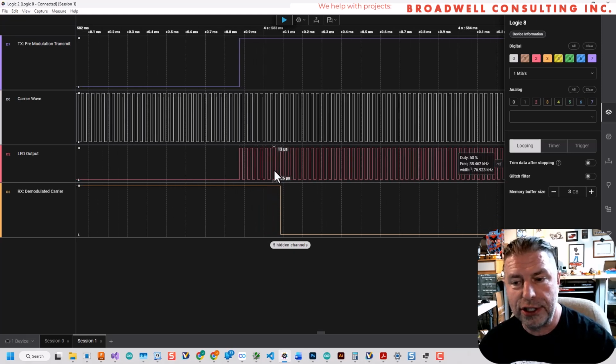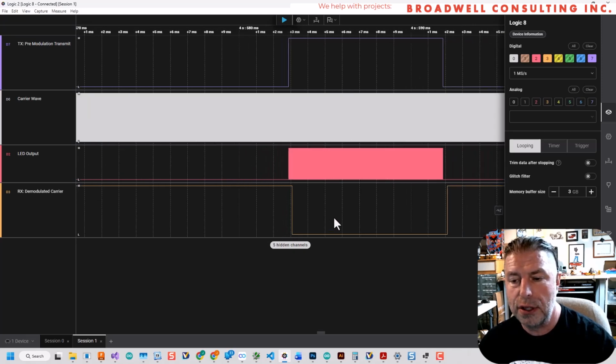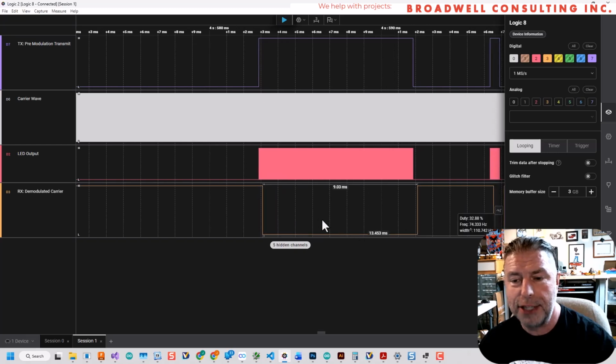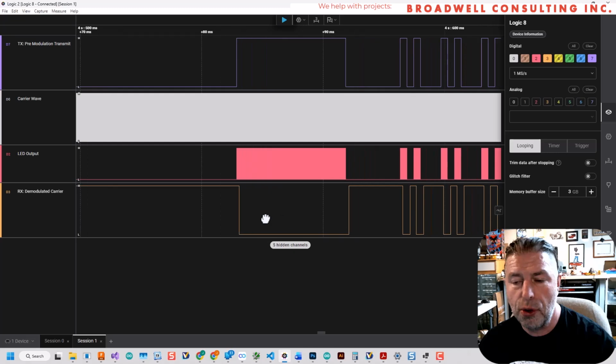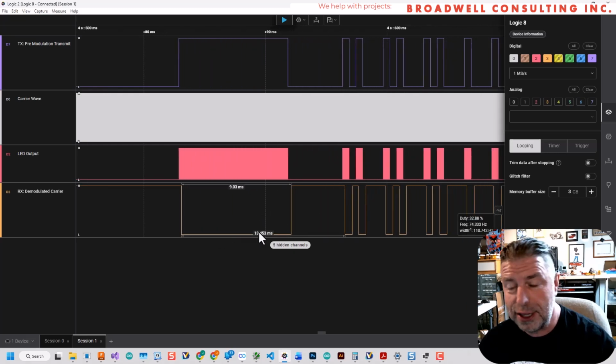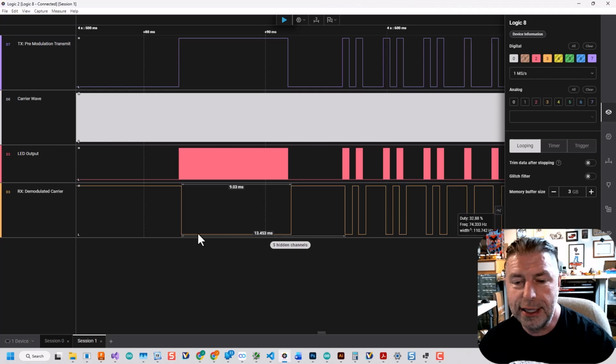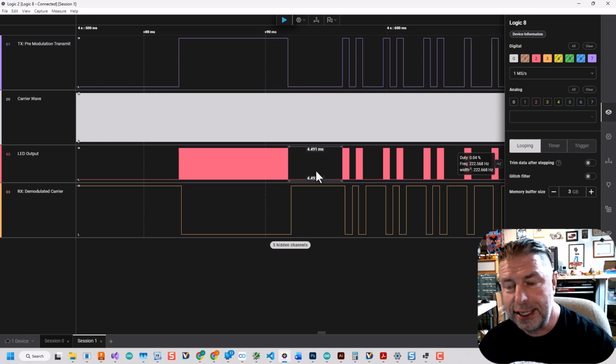The analog circuitry inside of the demodulator, a few pulses have to come through before it goes low. And again, we said most of these demodulator chips indicate active low, and so you'd want to be able to invert that going into whatever logic processing. In this case, a low signal indicates presence of a carrier, a high signal on the demodulation indicates absence of a carrier.